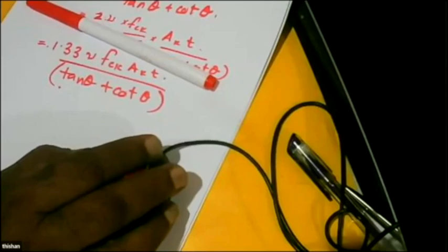No. Actually, what is the question again? Read it again. Isn't it better to have a shell element drawn to the length of the wall as a rigid arm, because a rigid beam may induce excessive torsional moment on the main beam? No. Actually, you can't use a shell element to represent the link. The question is whether a shell element can be used or a beam element should be used. Is that right? He's asking whether a shell element can be used for the rigid arm.